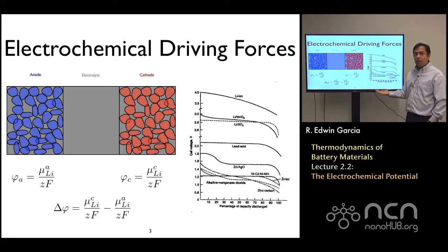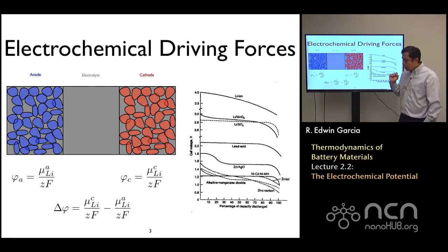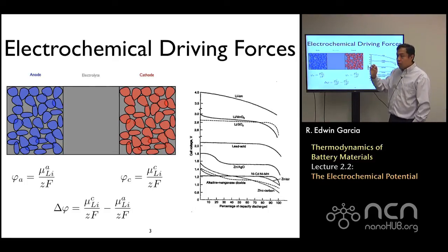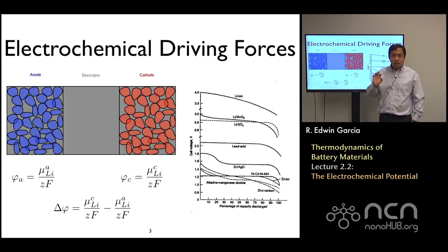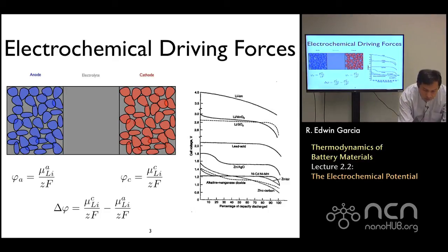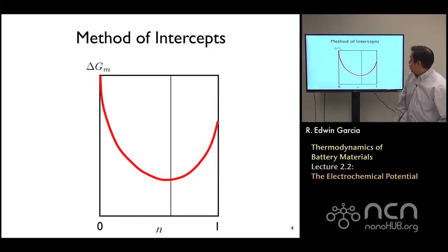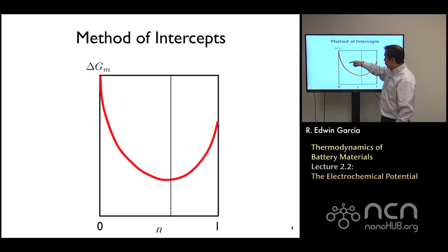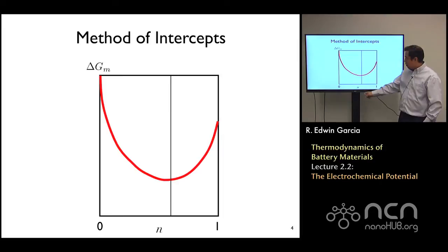So in order to do that, what we need to do is look back at the fundamentals as to how we can dissolve a solute in a specific phase or in a set of phases at equilibrium, bringing us back to concepts of thermodynamics or free energies of mixing, or thermodynamics of solutions. And well, here you have a sketch of that free energy. Okay, here the vertical axis corresponds to the Gibbs free energy of mixing. The horizontal axis corresponds to the concentration of solute.